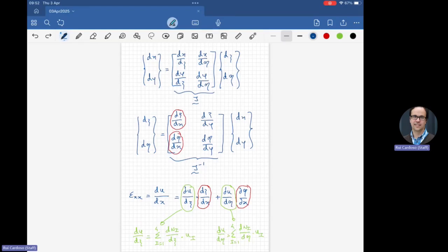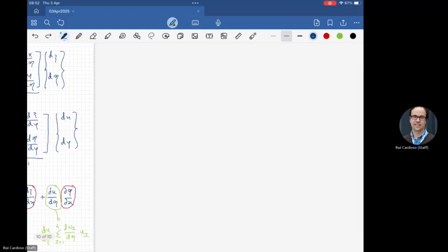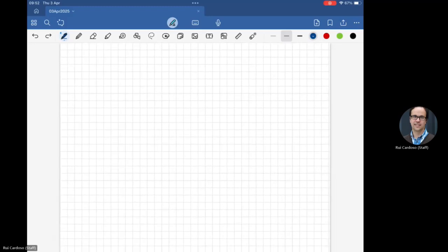But before we go to MATLAB, I would like to do a little bit of numerical integration, okay? So look at this. Another advantage of this Jacobian is in the numerical integration. You remember we did last week, for example, for the stiffness matrix, we need to calculate the integral in the volume of the element of this B matrix transpose times D times B, right? And we need to integrate this in the volume of the element, okay?